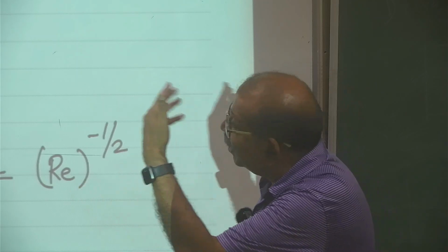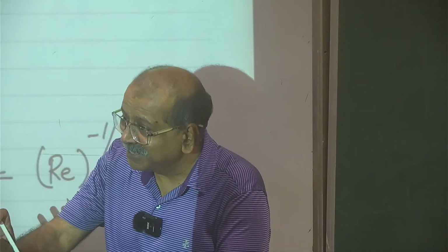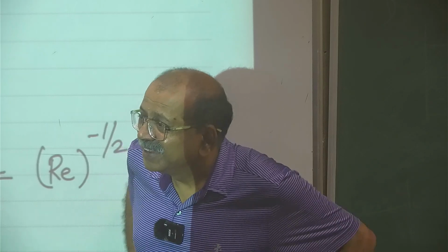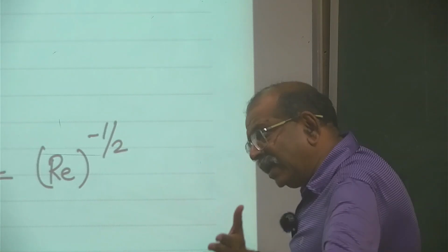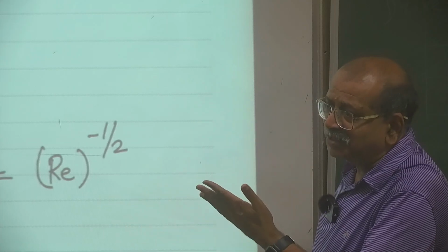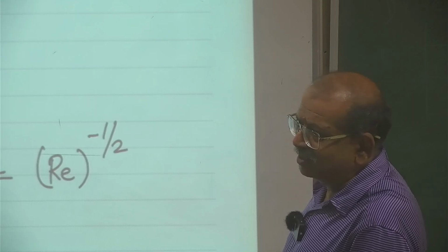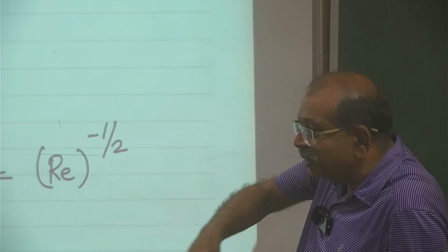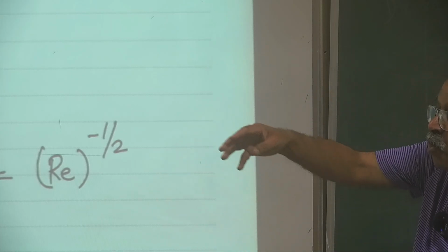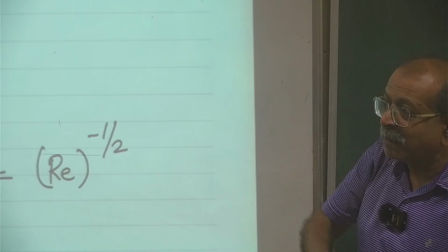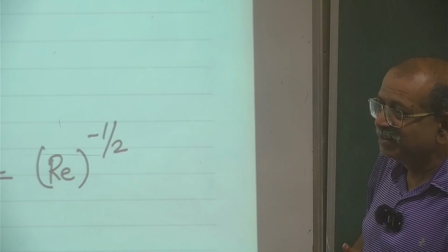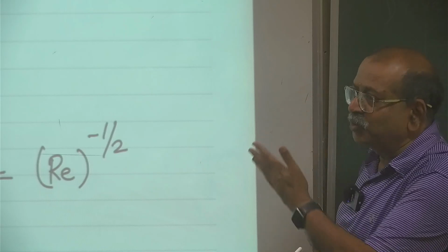What you are trying to say is, why is the convective term not 0, or of that order? That layer is thin, but in that layer, still the flow has to take place. Convection still has to take place. We cannot wish that away. Possibly that could happen in a case where we have a buoyant type of flow, where there is no capital U. See, here capital U is imposed.